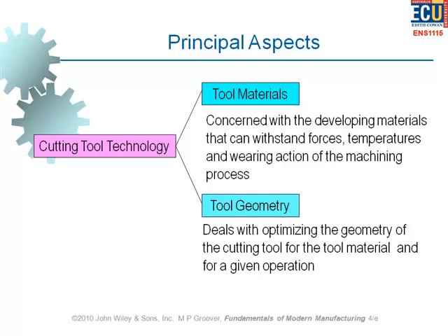So what you mean is that what is the material to be cut? That makes a difference. But what I'm asking is, in general, what we are after is a certain type of cutting tool when we are going to choose a type of material. What are the properties that we are after as a whole? Hardness. If a cutting tool material is not hard enough, it can't take the cut from the material. That's very obvious, right? What else?